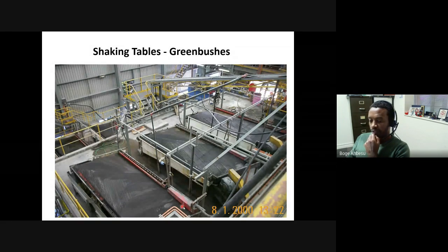So that's where the feed end is. And therefore particles are fed from here and they travel on the table in this direction. So if you see, these are the grooves I was talking about. So eventually large particles are collected here, and intermediate or middlings are collected here.